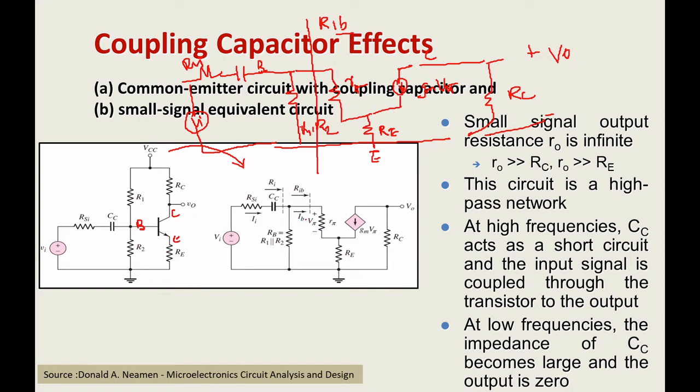So you can see here IB is coming towards this emitter terminal and IC is also coming towards it. So here it's something like 1 plus beta times your IB current. That is the reflection rule we studied earlier, right? Then another factor I have taken is RI. RI is the overall impedance of this amplifier. So I can write RI is nothing but R1 parallel to R2 and parallel to RIB. So what is RIB? That we will derive in the coming slides. Okay, you want to apply KVL and find it. I hope you are clear how this circuit is drawn in the small signal model.